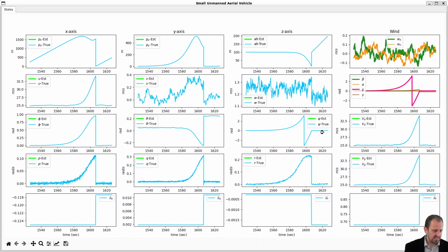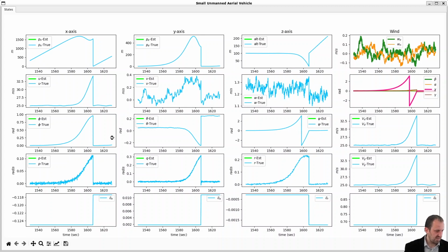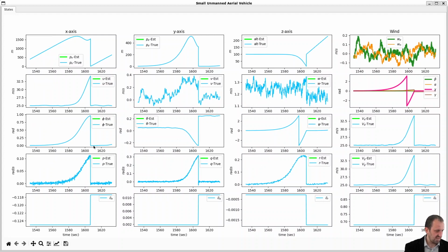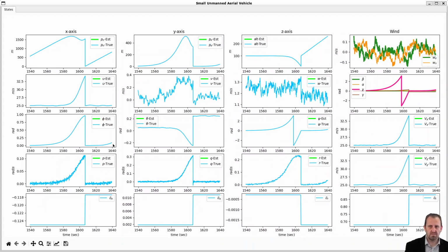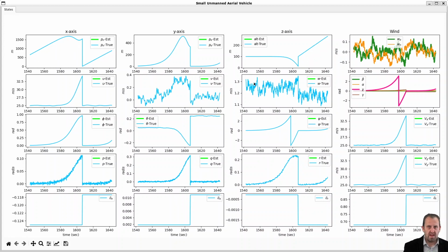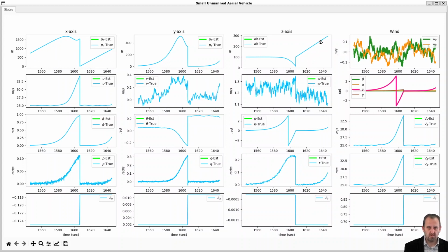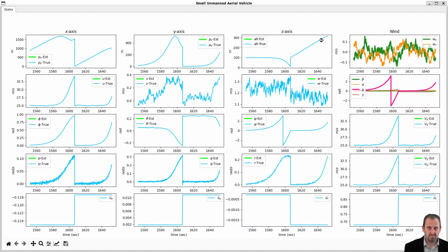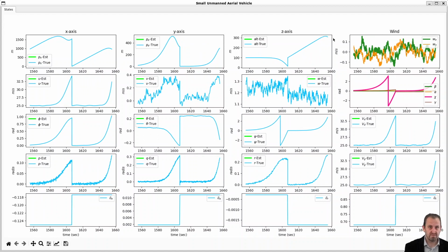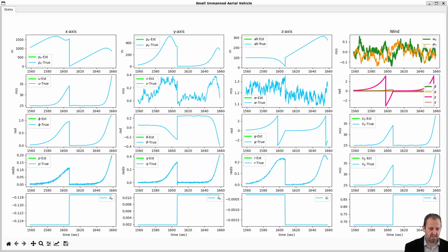We can see that our psi is staying around 0 and our phi is staying around 0, or at least it was nominally, until it starts to get off of its desired course, because we have no control keeping us back. Now that our z is back to something we can see, we see that we're increasing linearly with time in the z-axis, but now you'll see we're starting to fall off as we're falling away from our trim trajectory.